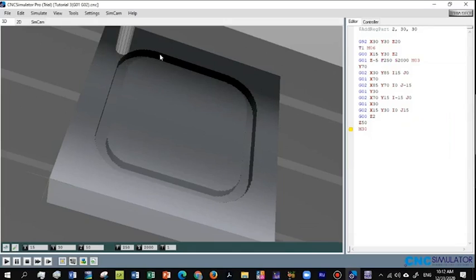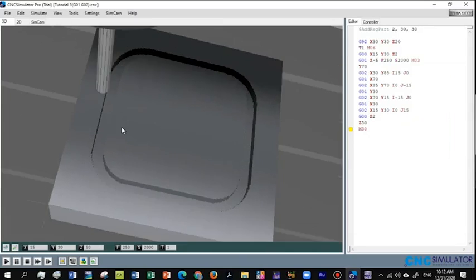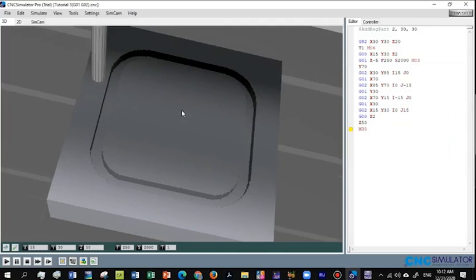When we are in clockwise direction, that means in all of this we are clockwise, clockwise, clockwise, so we use G02. If you are counterclockwise, you are going to replace this one with G03. So in this case, for the G02 or G03, we need to define the coordinates for the destination or the end point of the arc.